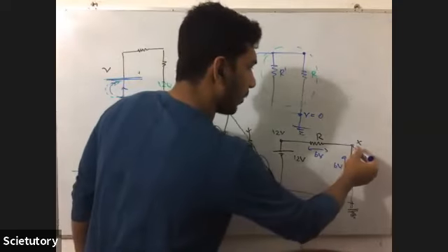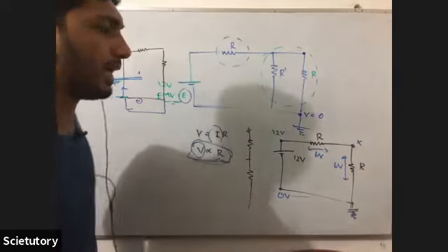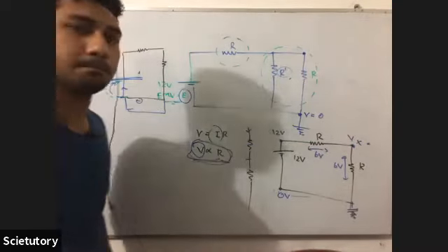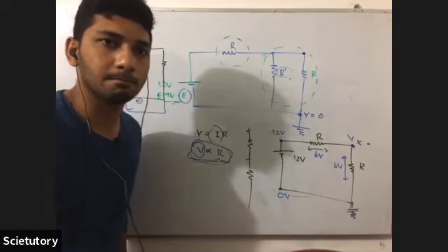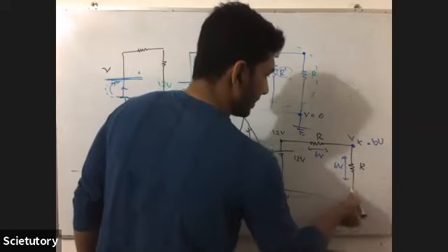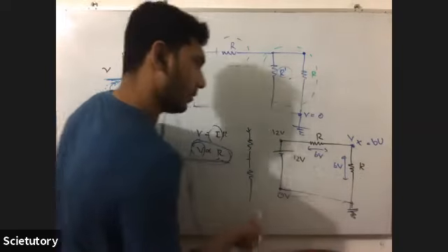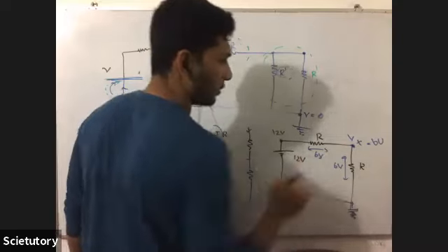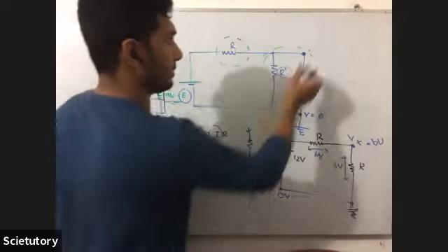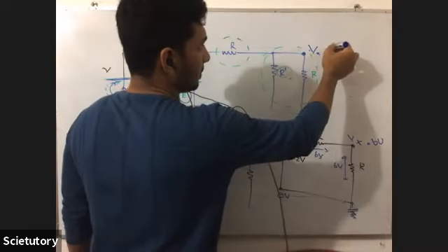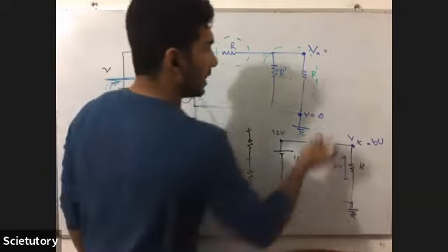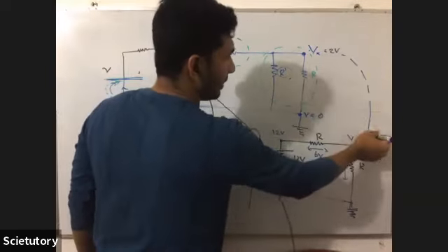Okay. So now, what is the point voltage of this point Vx after removing the R dash? 6 volt. Okay. So the difference is 6. If it is 0 here, this should be 6, or here 12, the drop is 6. So this should be 6. So what is the previous potential here? Previously, when R dash is connected, it should be 2. So now we can say it increases by 4.